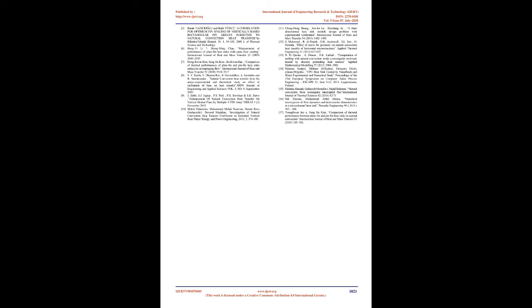The overview of the results of the present study involves CFD validation and a parametric study conducted for different configurations of fins at a constant velocity of 2 m/s in a duct, and a comparison made with aluminum, copper, and steel with 10 and 15 fin configuration models. Effects of heat flux and fluid. Maximum thermal resistance as a function of heat flux is also investigated here, considering water as the cooling fluid and assuming a velocity of 0.75 m/s. The heat transfer capability is dependent on the properties of the working fluid.